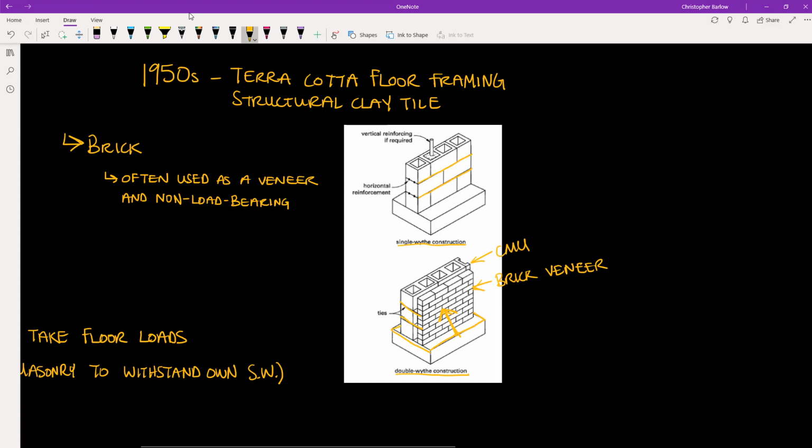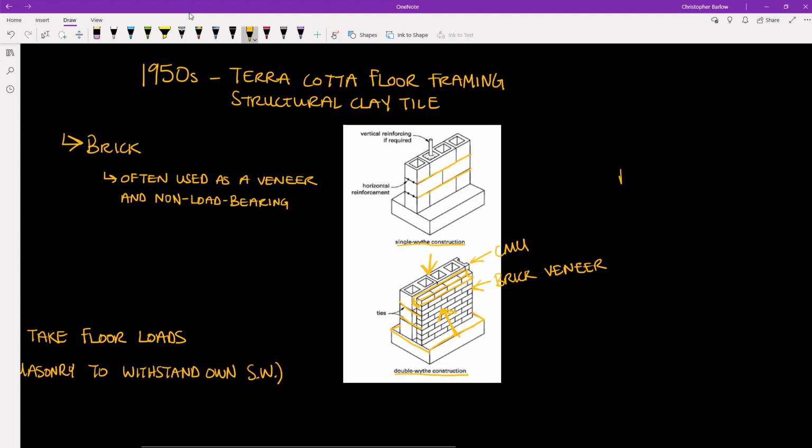However, if this were an upper level, we may have a relieving angle somewhere underneath this brick that ties back to the CMU. And that relieving angle would be to support the brick under its own self-weight. And the locations of these relieving angles will need to be coordinated with both the architect and the structural engineer, as they can slightly change up the look of the brick facade.